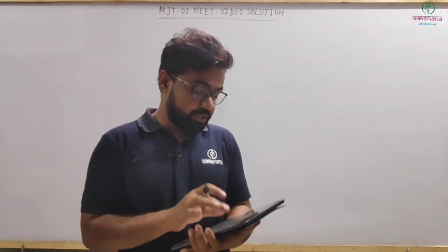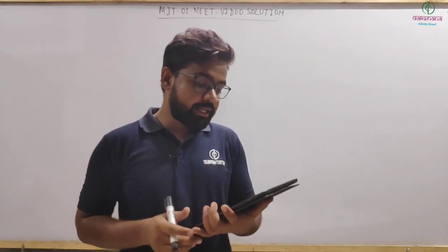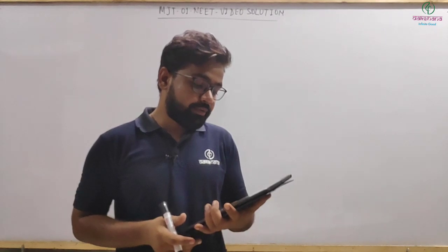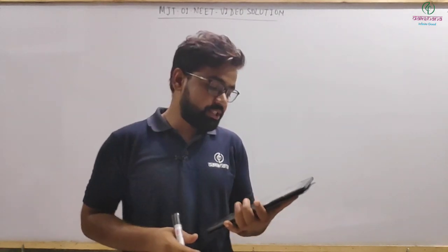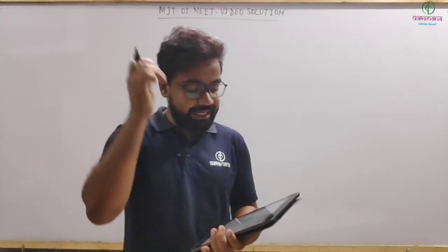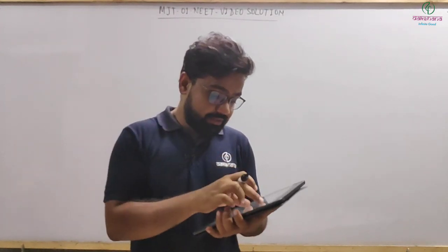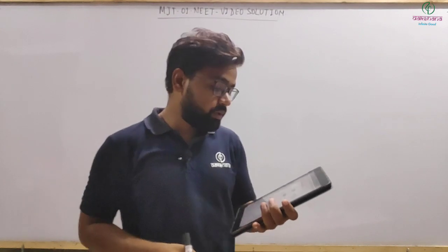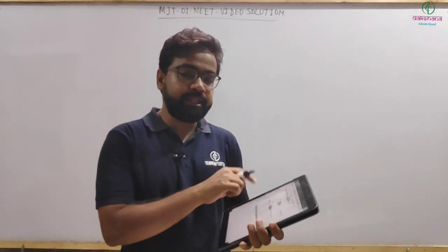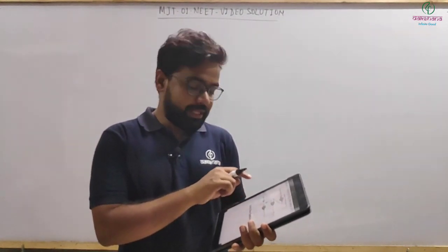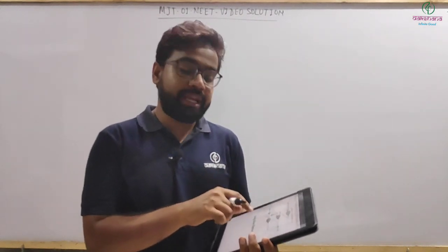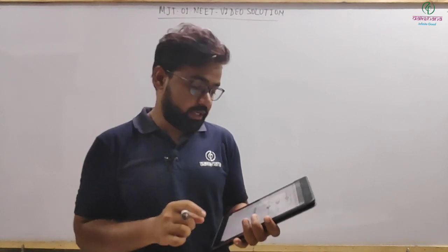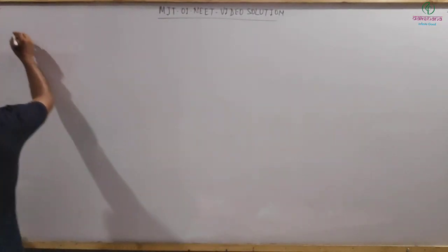So here we have question number 1. In the circuit in the following figure, the value of y. Here you have three gates given, G1, G2, G3, all are NAND gates. So here we can start from gate 3. In gate 3 both inputs are initially 1, then the inverse by the NOT gate is 0, so 0 0, then the inverse of that will be 1 output.